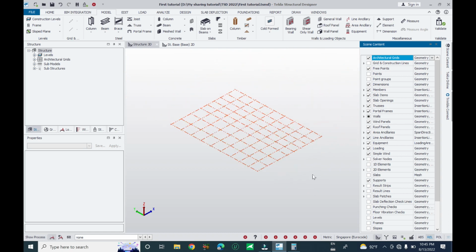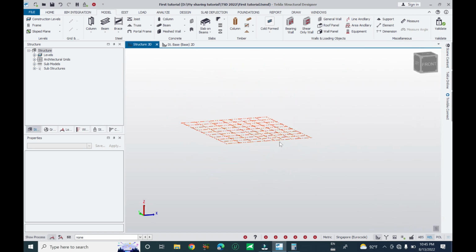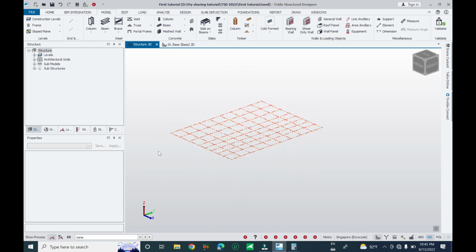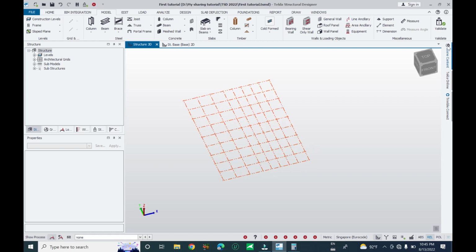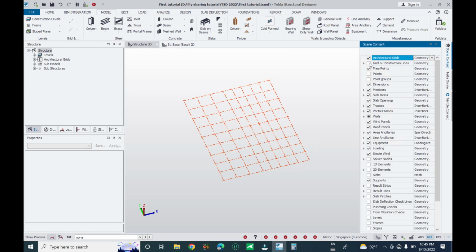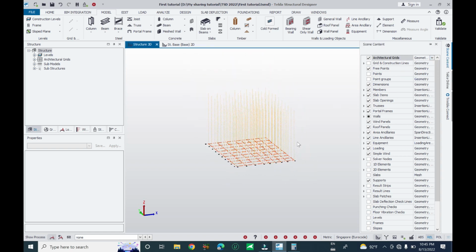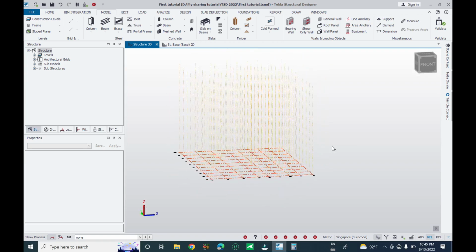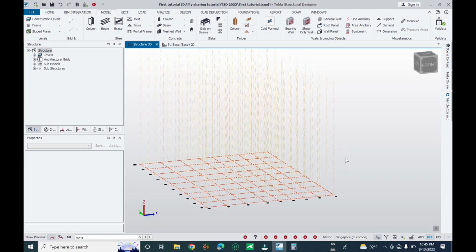Okay, or you can show only geometry, do not show detach. Okay, use the right mouse to rotate. This is the way you can rotate the view. Right mouse, and again click on it, click on the architectural grid. Now we want to display detach vertical line. Now let's start. This is the way you can add the grid for the horizontal and display for the vertical line.